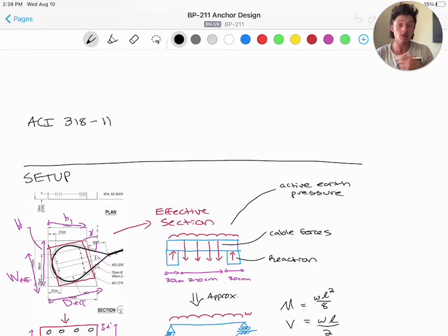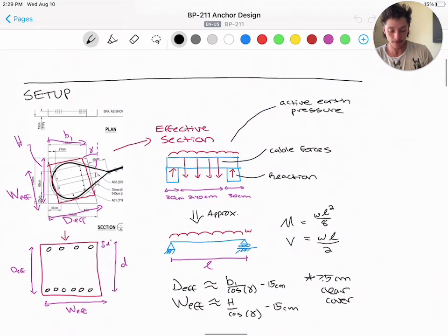In another lecture, we'll talk about this in the context of the early strength of the concrete, and we'll adjust our compressive strength of concrete accordingly. Now, in the following diagrams, we'll estimate the beam section formed by the largest rectangle you can draw perpendicular to the loading. And that's shown here.